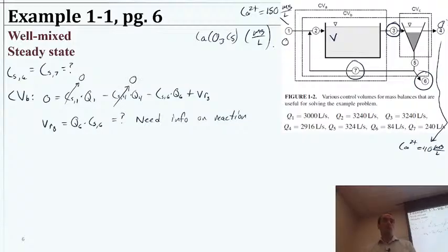So it does simplify our setup very nicely to understand something about the reaction term. That would mean that the amount that we are wasting out this discharge pipe is exactly the same mass rate of change as we are growing in this reaction chamber, given this control volume. That's quite convenient, but we still need to know something about this RG value.